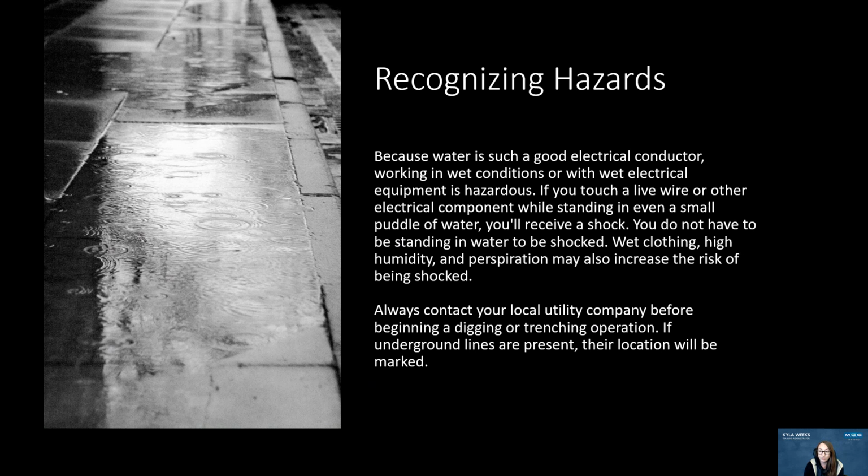Always contact your local utility company before beginning a digging or trenching operation. If underground lines are present, their location will be marked.